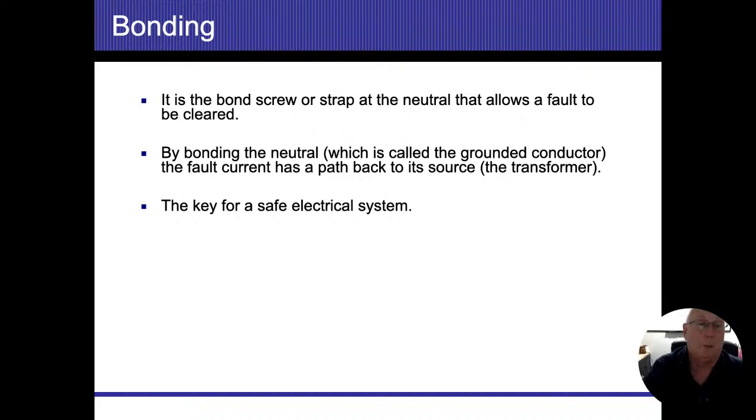So if I'm having trouble finding my GEC and I'm inside the panel, one of the things I could look for is in my conduits, there should only be one, maybe 2. If they go one to the water pipes and one to a ground rod outside, I might have 2 of them. But there should be one wire inside that conduit all by itself. If any other wires share and go in there, that's going to end up being a problem. Nothing else goes in with that GEC.